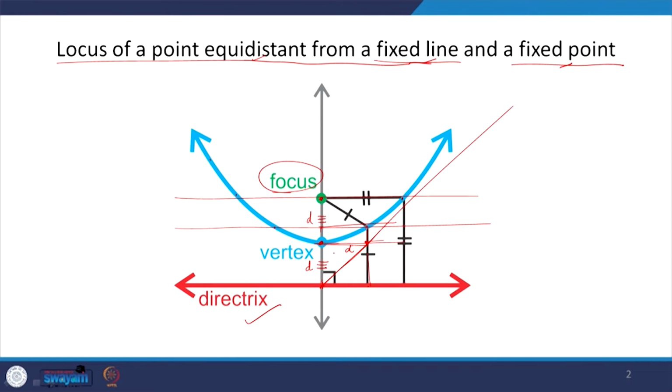So what we will do, this distance is the distance that will be on this line, and if I take the same distance from focus f, or from this focal point f, I will get a point. So what I am getting actually is this distance, and I will cut it onto this line, and I get a point, the points of a parabola. This was exactly the similar process which we used to draw hyperbola. The only thing being, it was not equidistant, it had eccentricity.